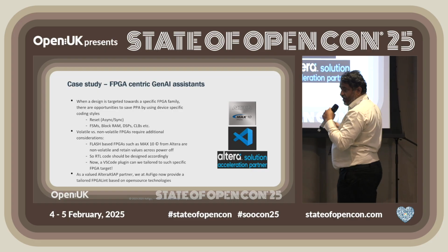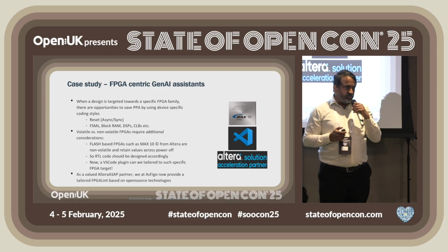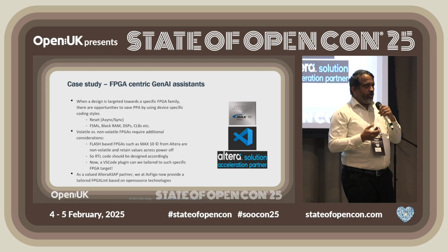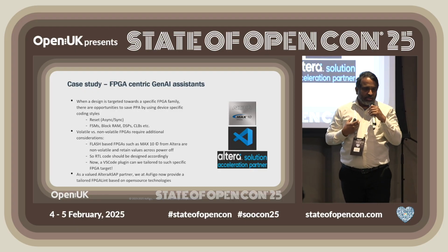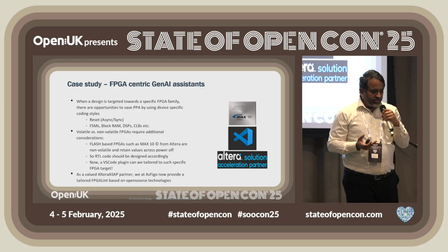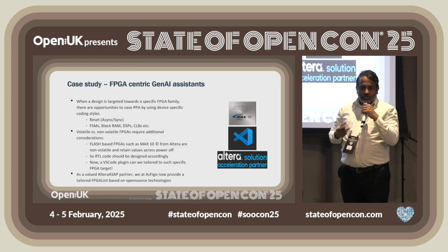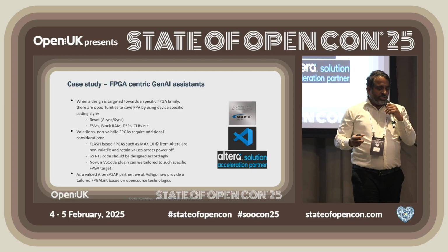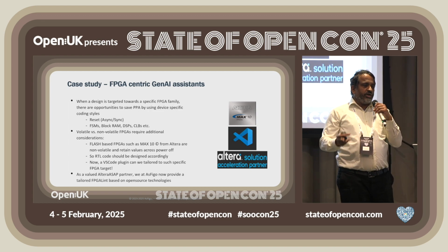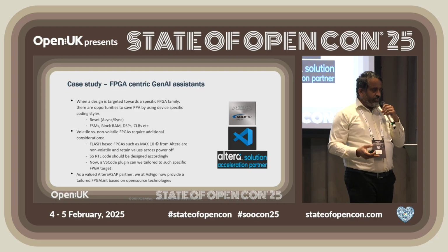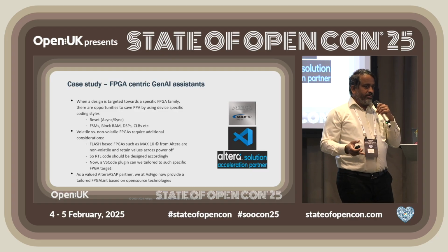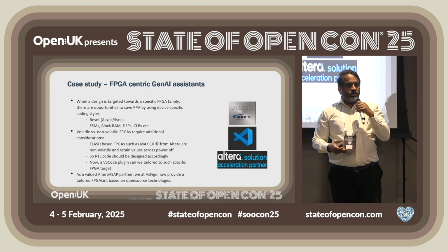The same thing goes for FSMs, finite state machines. Do you want to reset every flop in there? Technically, in an ASIC world where I come from, I started with ASIC back in the '96, '97 timeframe. That was the golden rule. Do not worry about it, just reset everything. If you do not reset, something will go wrong in the field. Now, fast forward, you start getting into FPGAs, they say, no, don't do that. Because you're going to consume additional resources.